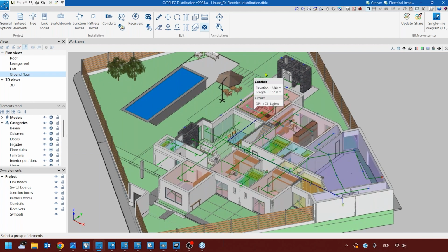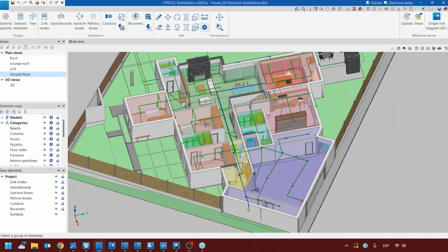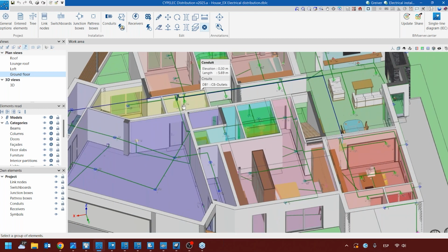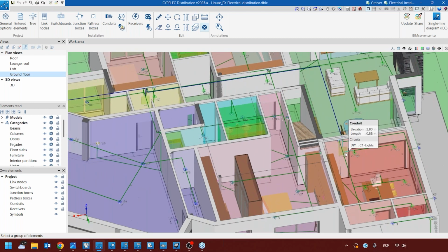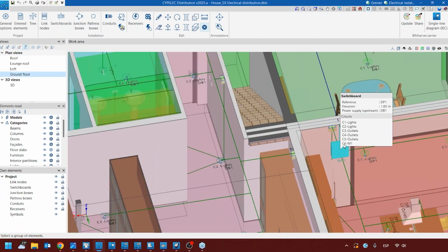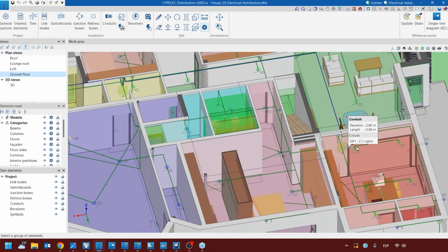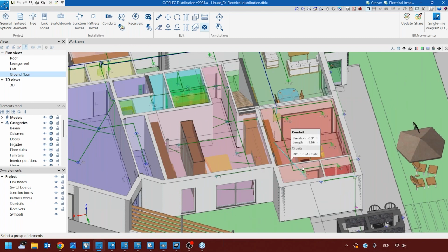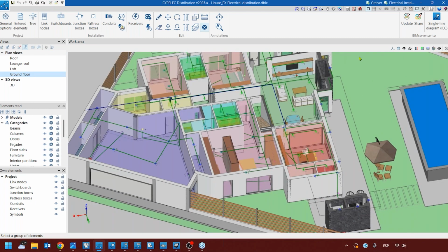connect them. But before doing an example in here, I would like to show you how this has been designed. For example, here you're going to have a distribution board, which is the one that you can see in here. This distribution panel is going to be in the kitchen. In this distribution panel, what I'm going to have is all the electrical outlets that I have in the kitchen. The rest of the electrical outlets that I'm going to have in the outdoor, for example, the motor for the pool, and the rest of the lights that I'm going to have in the outdoor.